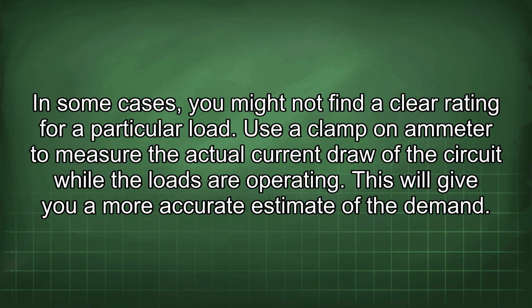In some cases, you might not find a clear rating for a particular load. Use a clamp-on ammeter to measure the actual current draw of the circuit while the loads are operating. This will give you a more accurate estimate of the demand.